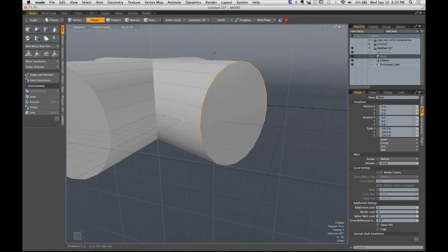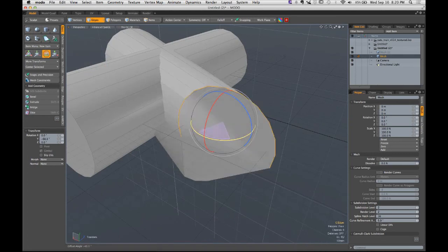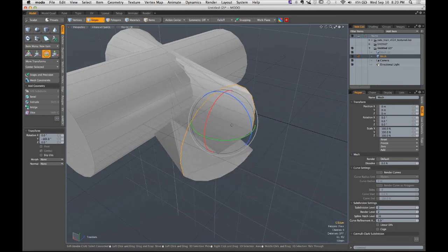Sometimes people work and they only have a couple of edges here, and they'll scale it down. They'll do that. That's bad. We've crossed all the edges. Now they're going the opposite direction. Sometimes people rotate things oddly. Believe it or not, it seems kind of silly, but people have done this in the past. It happens sometimes when you don't even know that it's happening. It's very easy to think that you're working on one side of your mesh, only to discover that you accidentally had another polygon selected, and it's transforming, rotating, and scaling both of them at the exact same time.